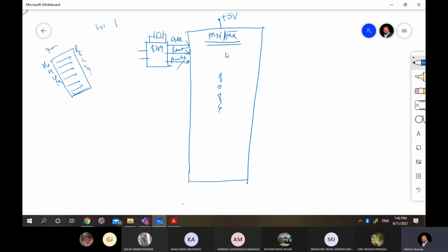So that's why this particular thing is important. So this is the first: we must use the clock generator to generate a clock, which is given to the 8086. And now the next important thing is that we need to demultiplex the multiplexed lines, which are address lines now.